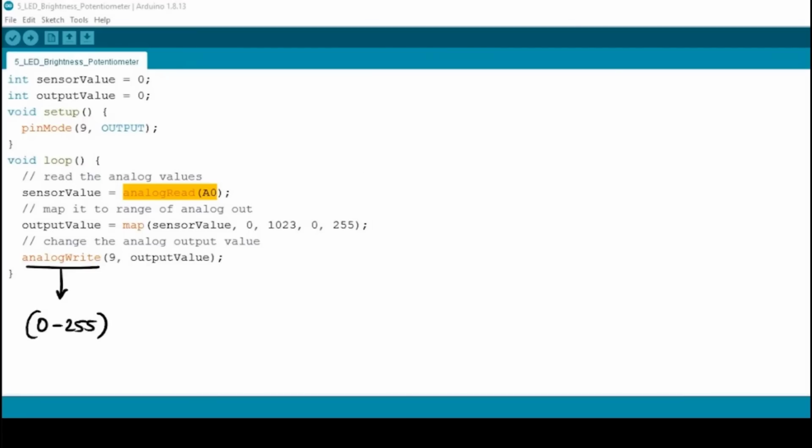So what is actually happening is that across the potentiometer, you have values between 0 and 5 volt, depending on the position of the wiper. Because voltage is proportional to resistance, wherever is the maximum resistance, the maximum position of the potentiometer, that corresponds to 5 volt. The reading can be anything in between, depending on where the wiper is.